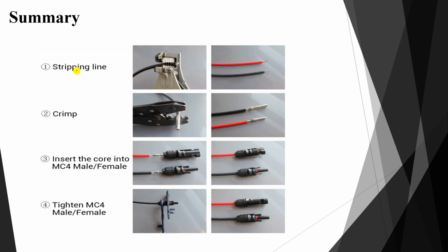So we have the stripping part, which removes the insulating material. So we'll have something like this. Then I'm going to connect this part, add it here, and connect my own wire. Then compress a little bit, just a little bit, so that it will be fixed to this part of the wires. Then I'm going to insert it into the MC4.